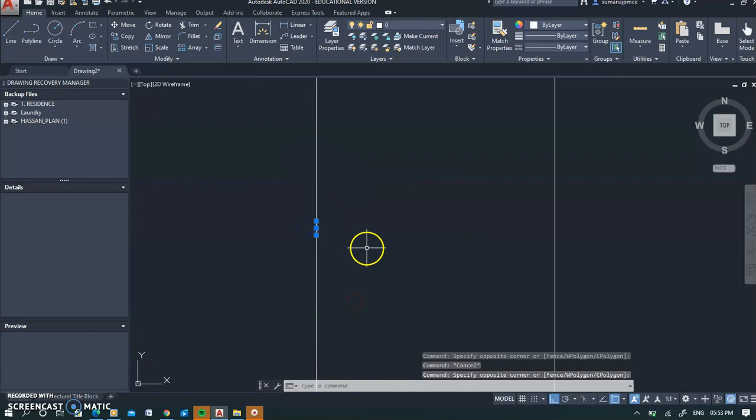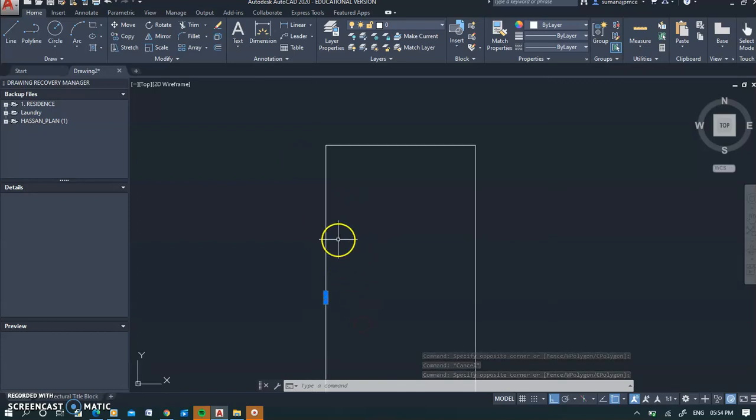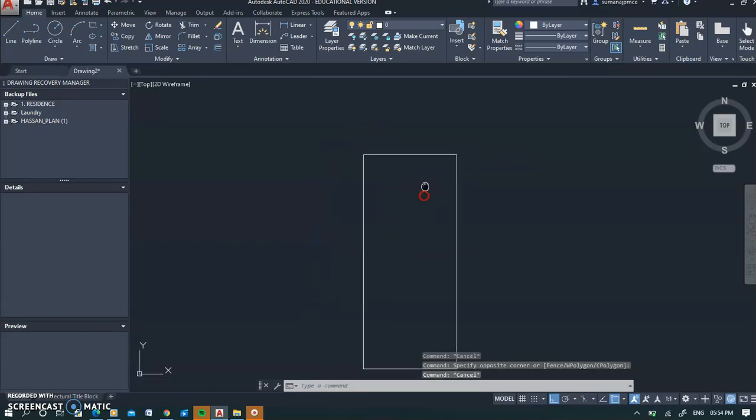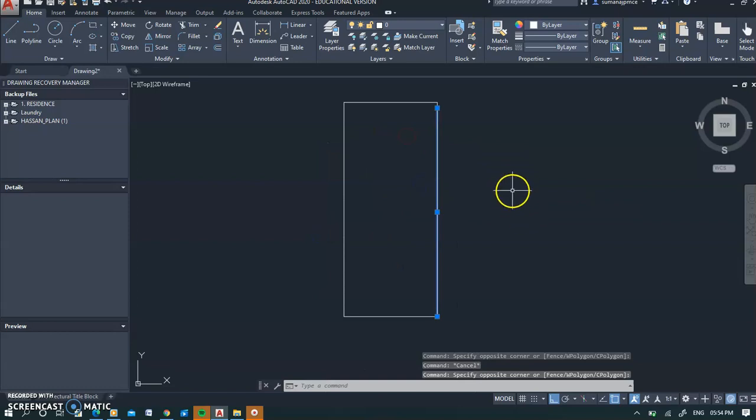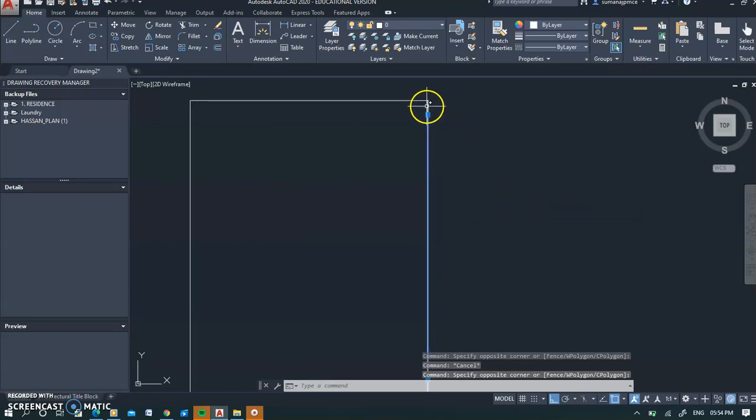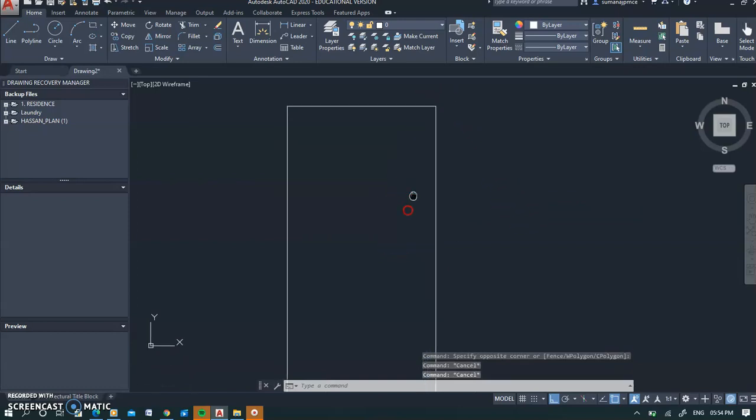Then I wanted one more wall thickness, which I forgot. So I moved that line by 0.3 and created that wall thickness. And then I have this line again 5 meters. This line is 5 meters, and I have just joined it from there to here. This is the mistake, so this is that extra 0.3 which I've added later.